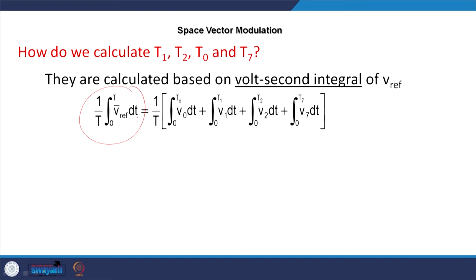which you know, as you require to inject the voltage at 35 volt at an angle of 45 degree. Generally, if you have a 45 degree injection, of course T1 will be equal to T2, because V1 and V2 are equal in magnitude.